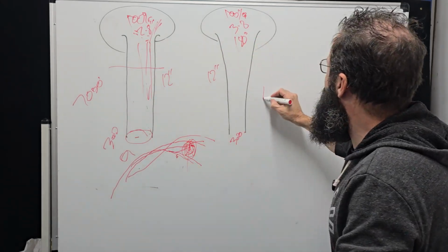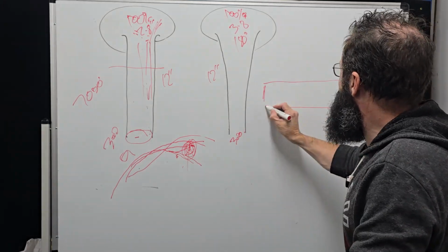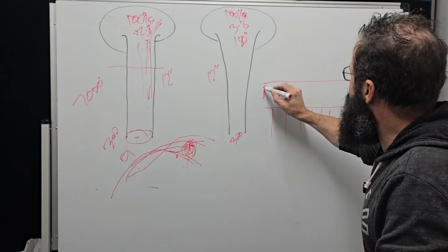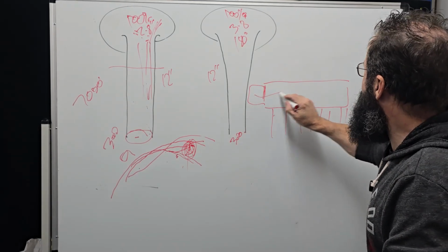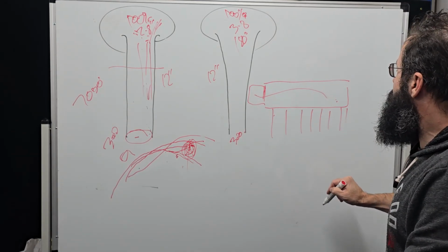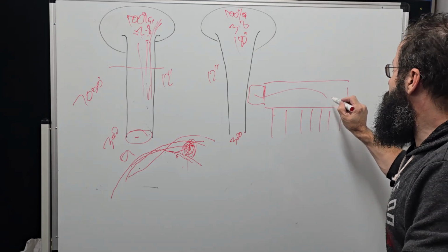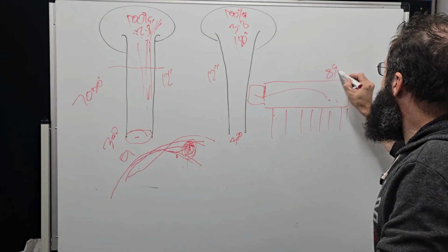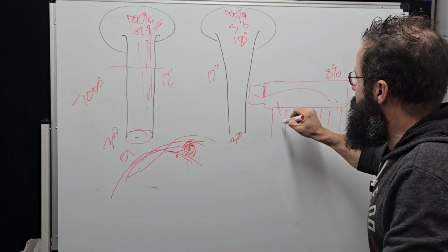So if it's a biased plenum, if we just have a plenum like that with our 4 runners each side and the throttle body there, well, the air getting to this cylinder is going to struggle. I reckon, at a quick guess, it's going to be 8% down on VEs in this cylinder compared to this cylinder.